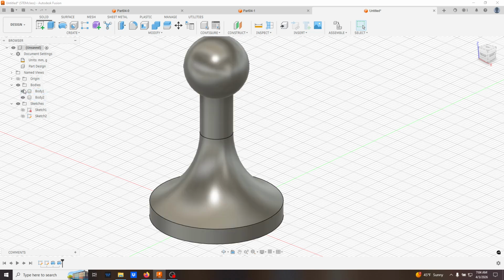Now, this can be helpful when it comes to design. A lot of times when people are doing stuff for 3D printing, I like to design this way. If I'm trying to have parts that fit with other parts, I'll model one thing as solid and then put it inside of the other one, so that I can just do a remove of it. And given that each of these has its own sketch that it's linked to, it gives me a little bit more flexibility in design.